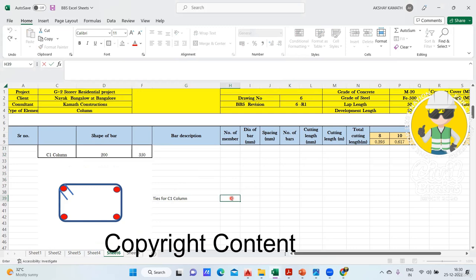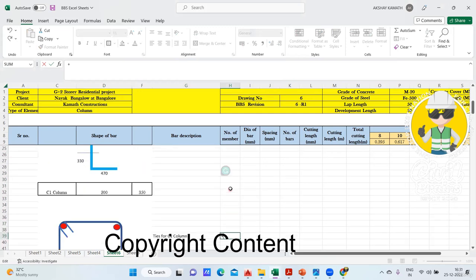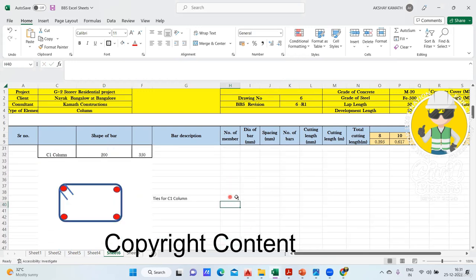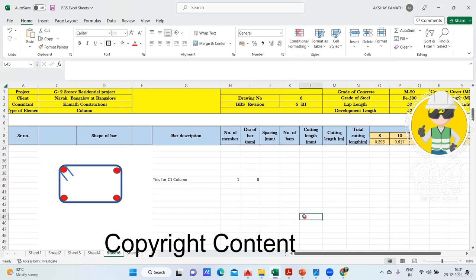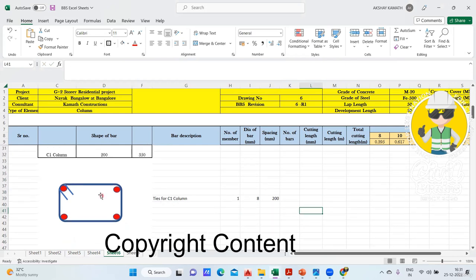Number of member, how much? 1. So here you don't write 1. Whenever you write here, you have to interlink to this. So by default, the moment you write there, it will be interlinked here. Okay. Dia you don't have to interlink because dia will be 8 mm usually for this. So write 8 mm. Spacing was 200, right? 200. Fine. Okay. Now we'll find this.